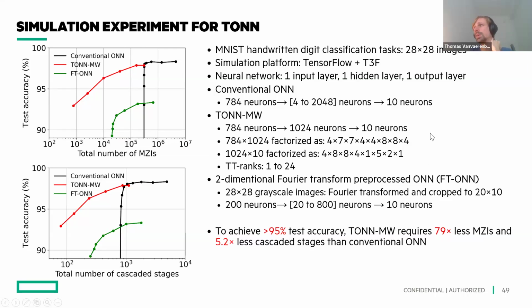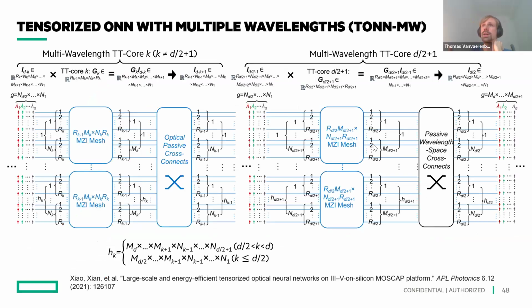So far we see that for this example, MNIST, the vanilla toy example that everybody starts with, it seems to work. But for some other use cases, it's possible that your factorization algorithm is going to give you sizes that are very hard to achieve with photonics. If that were the case, then maybe the solution wouldn't be very good. Or you might need to think about which dimensions you are going to shuffle into wavelength division multiplexing, and which dimensions into spatial multiplexing. So there's that type of trade-off.